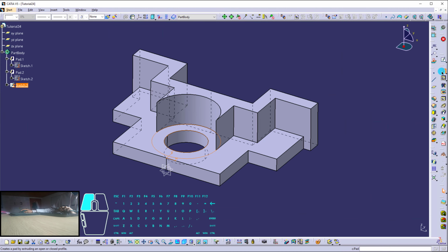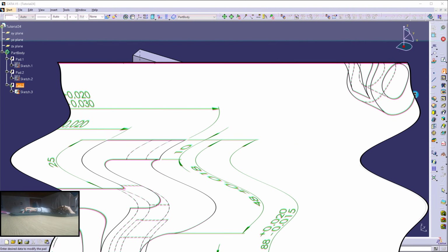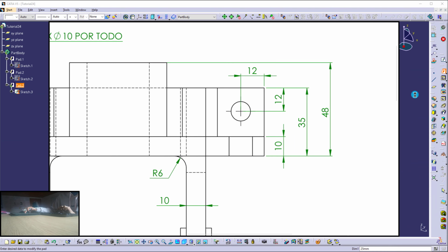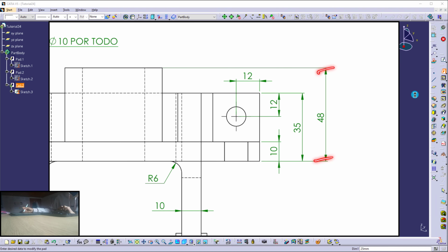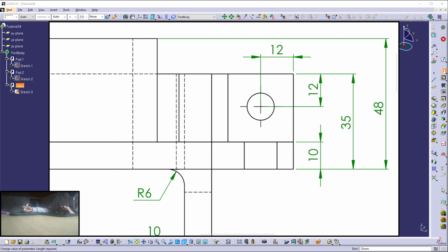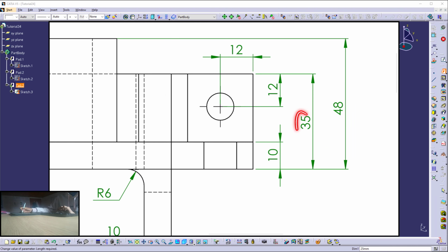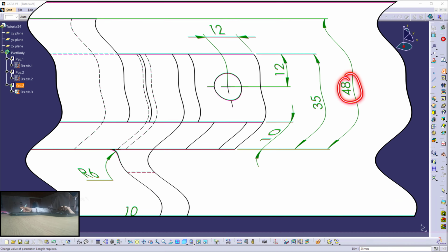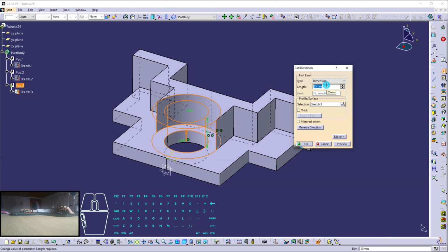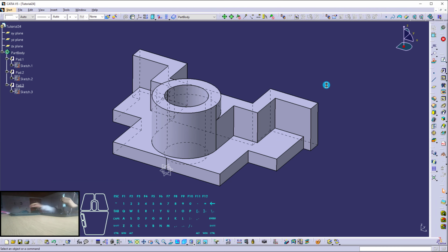and I'm going to extrude this using the path definition tool. I'm going to extrude them 48 millimeters minus 10. Why is that? Because remember that I'm creating the sketch on this face. So right here I have 38.5 and 48. Now this is going to be to 38 millimeters. Enter. Right there we have it.